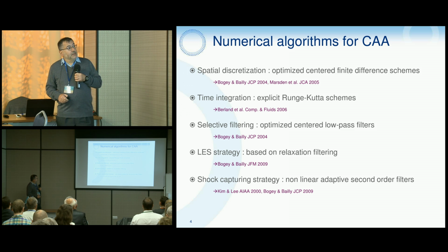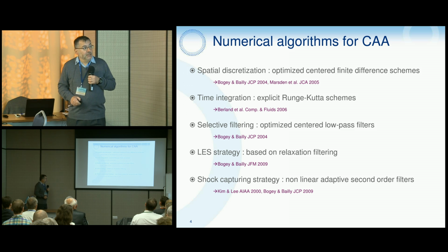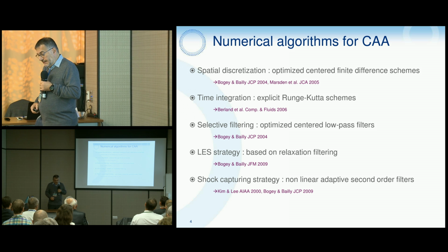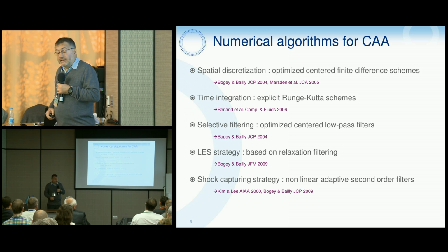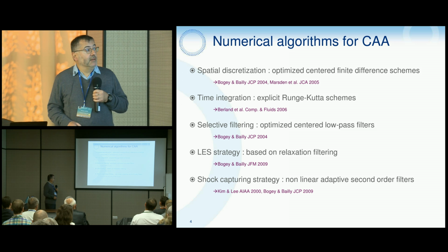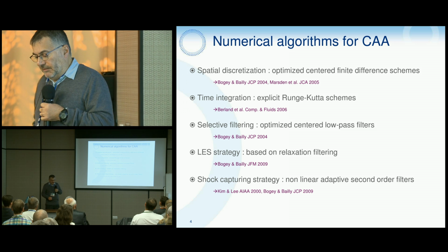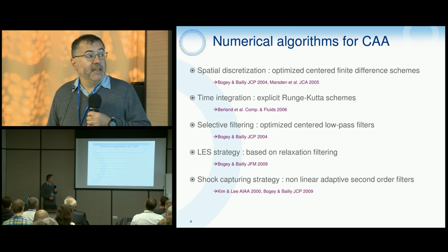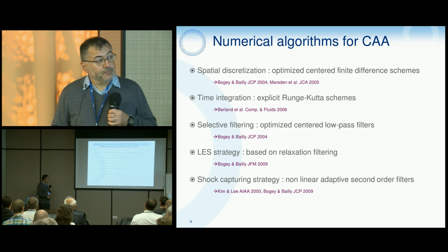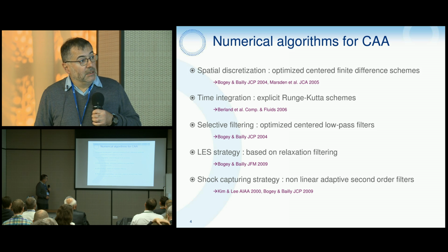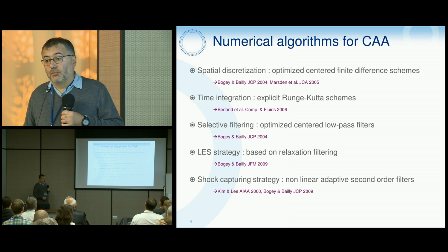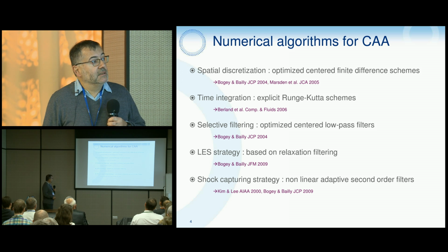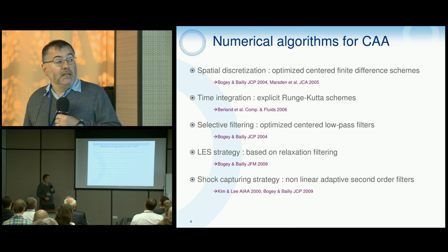For the LES strategy, we also follow the approach developed at Ecole Centrale, mainly based on what they call relaxation filtering, which in fact doesn't use any subgrid scale model. As I said, we have to deal with compressible and shocked flow, so we added shock capturing strategies.